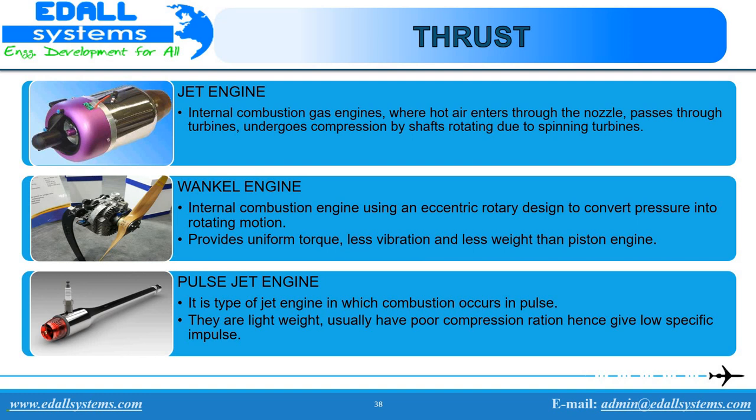Pulse jet engine works by alternately accelerating a contained mass of air rearward and then breathing in a fresh mass of air to replace it. Energy to accelerate the air mass is provided by the deflagration of fuel mixed thoroughly into the newly acquired fresh air mass.